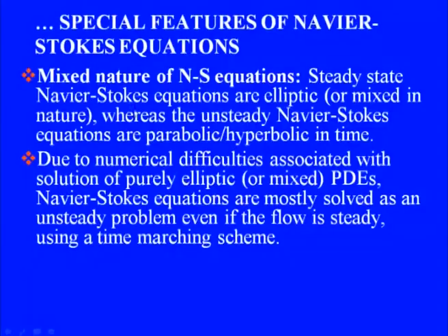So, there are numerical difficulties which are associated with the solution of purely elliptic equations in the case of steady state incompressible flows, or mixed PDEs in the case of compressible Navier-Stokes equations. We rarely attempt to solve the steady state Navier-Stokes equation in either case.